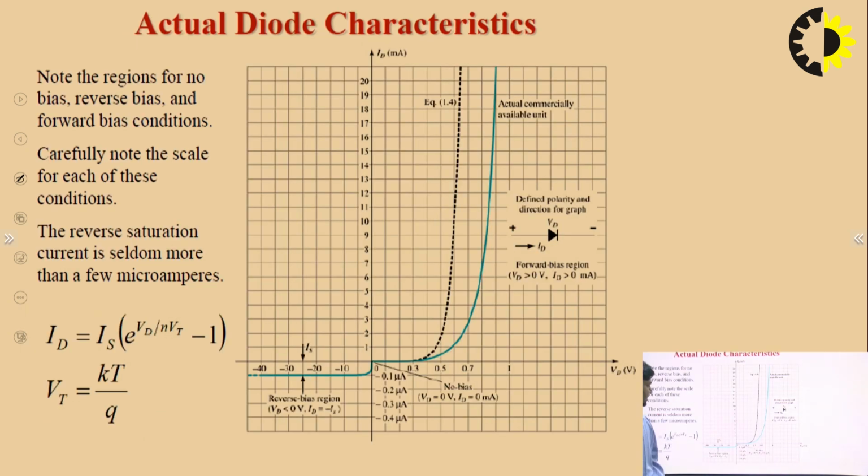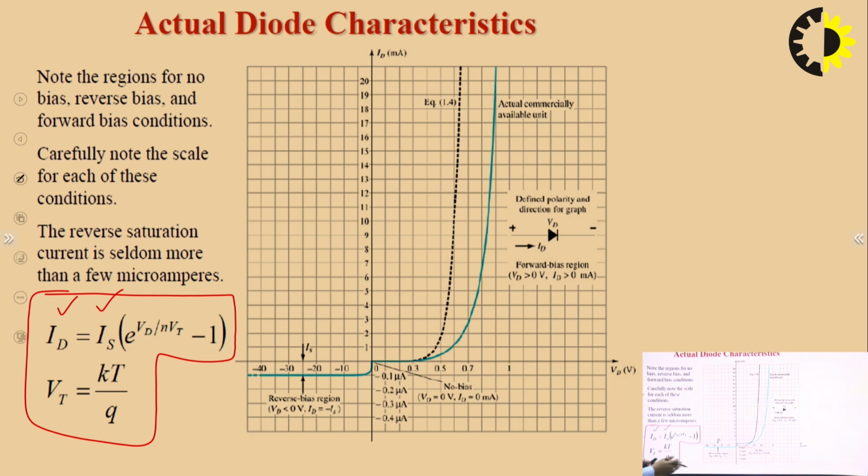This is very important and has to be asked in the AKTU examination. So, what is the diode current? It is the basis of the behavior of the PN junction diode. If we plot the diode current in forward bias and reverse bias, what is the relation between them? So, this is the diode equation, ID is equal to IS e raised to power Vd upon eta Vt, minus 1.